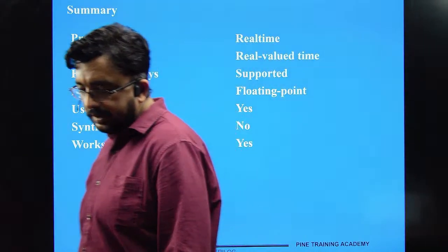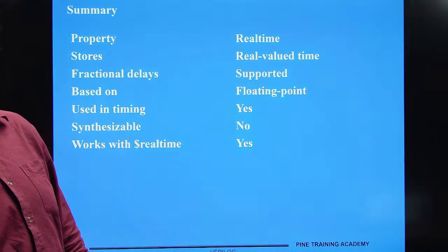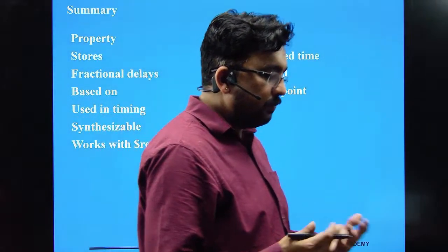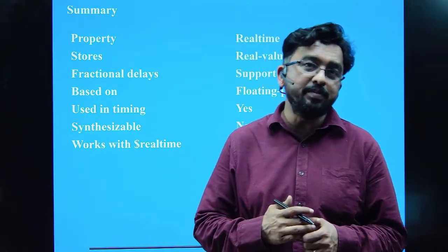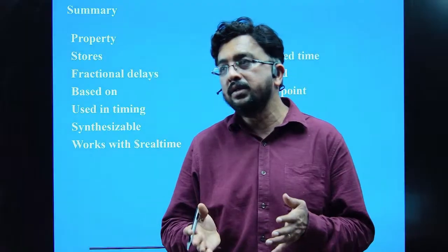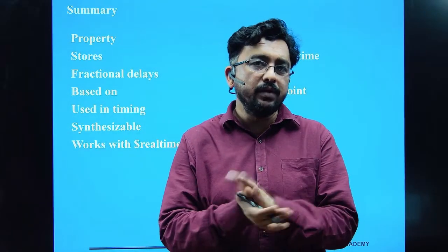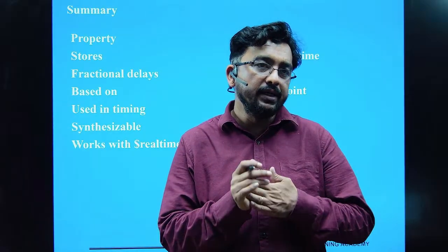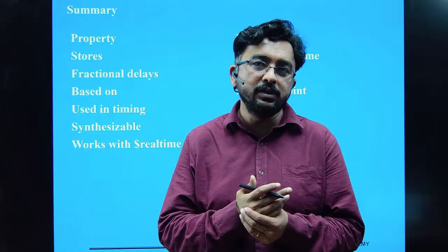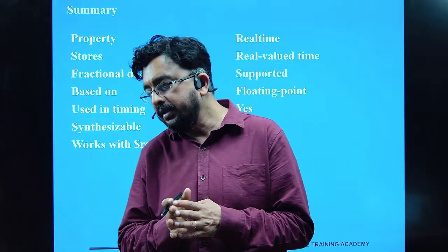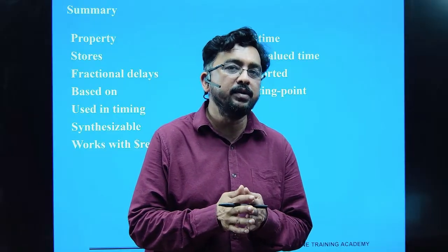Okay, so this is what we covered today. Now a few more language elements are pending, like vector and array. I will take care of that also, vector and array, because real and real time we generally don't use if we are writing synthesizable code.